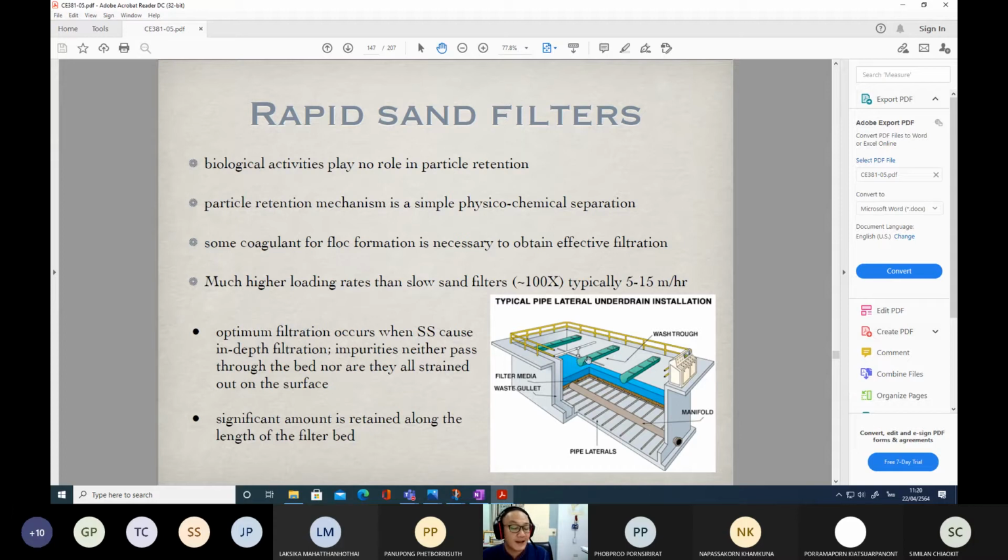Finally, we let it go for at least half an hour, so that water flows in the opposite direction. So wash-through channels actually act as the effluent channels, receiving the water after it is used to clean the filter media. So we feed the clean water through the manifold just for cleaning the filter media.